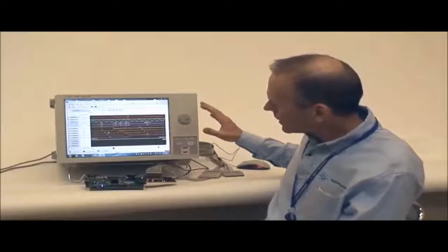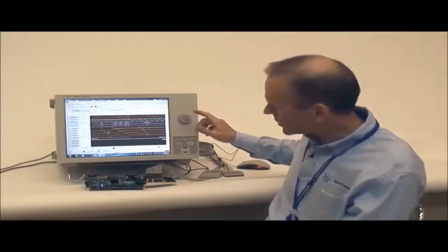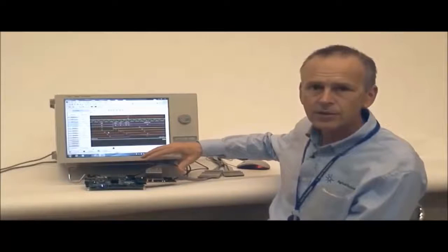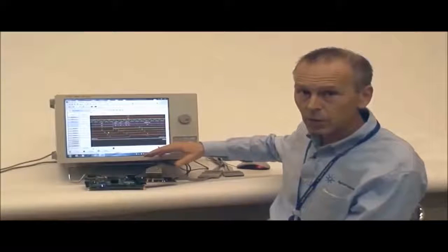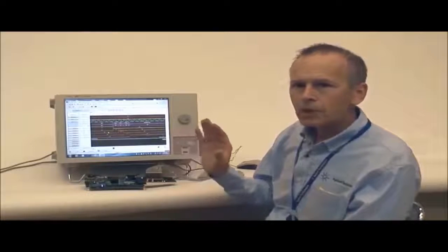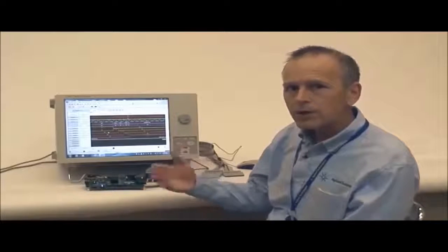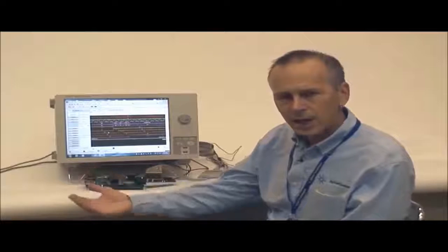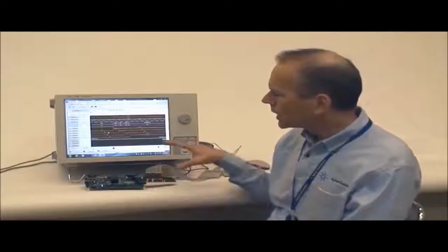So we have taken a 16850 series logic analyzer, we've attached it to the device under test using single-ended flying lead probes, and we're going to look closer at what's happening in this design. It should be sending out a 5-bit state machine that runs it through the paces of sending out the data, and each time it sends out the data, it should get an acknowledge signal back saying, send more. But something's gone wrong.